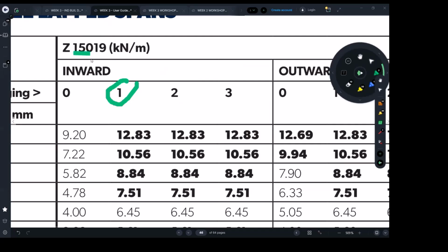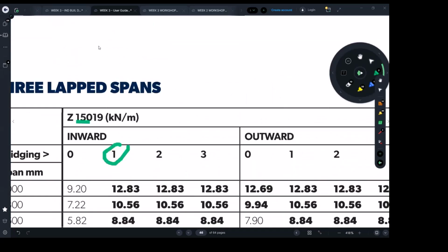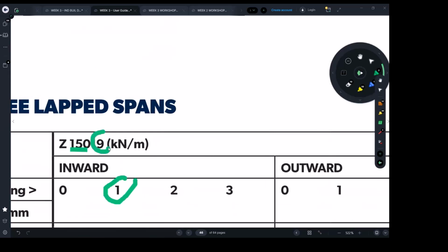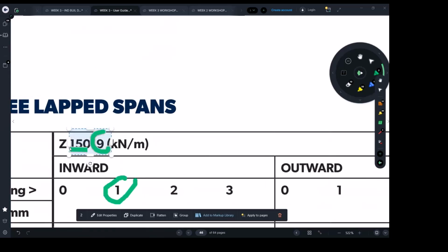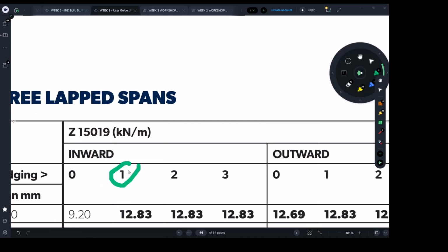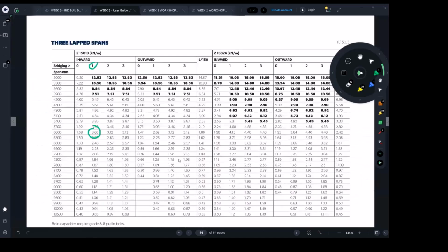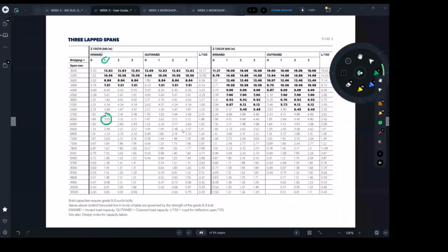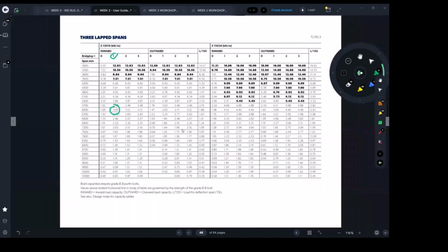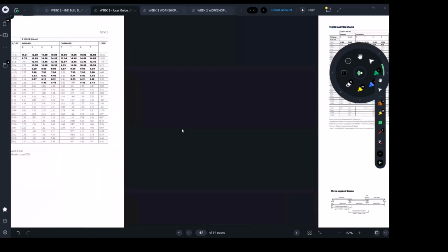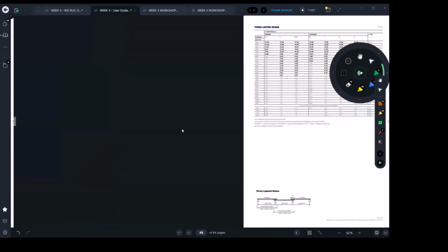The first 3 numbers give you the depth. And this one talks about the thickness of the steel. You've got different thicknesses, and you need to read those carefully. At the start of the document, it talks about such information. I strongly suggest you look at those tables.